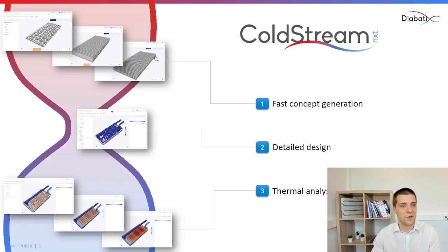Try your wildest in the first stages, but then narrow down to a couple of variables in detailed design. And lastly, when you have optimized for a given operating condition, and you want to know how that design performs for different operating conditions, you can then widen again for the sensitivity analysis in the thermal analysis phase of the design cycle.